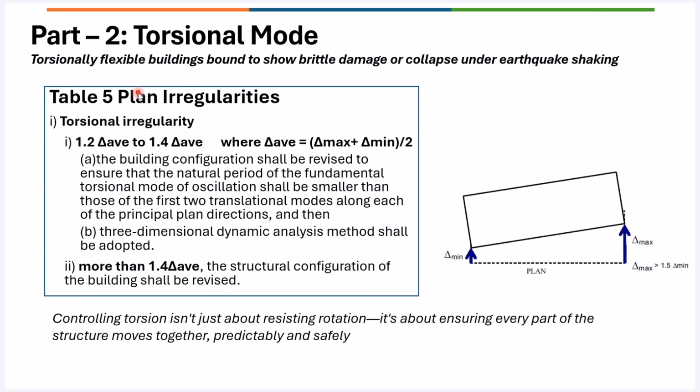So why am I mentioning this? These are the strategies, the only ways to control the torsional mode, the weakest mode, and the program is very well capable of handling all types of analysis that are required for TMD or base isolation, or providing a real-time earthquake as an input and studying the response of the structure.